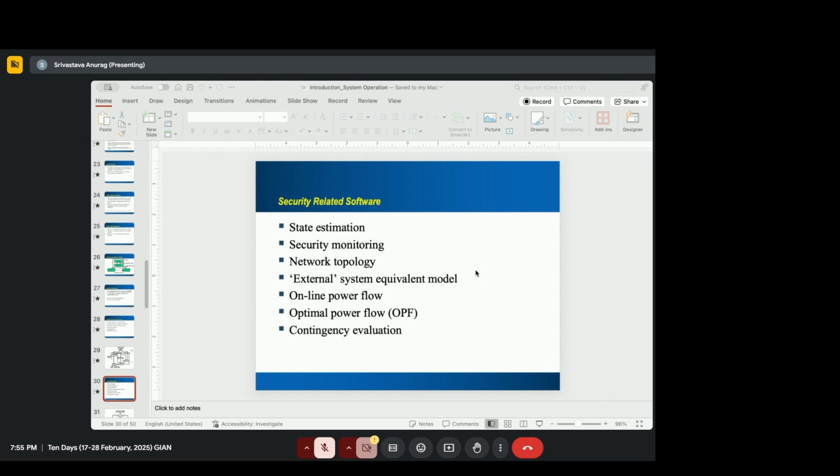Okay, going to the next question. How frequently is the load forecast updated in distributed state estimation or security analysis? So load forecast is at the same scale at which we solve power flow, right? So it's in minutes, typically 5 minutes, 10 minutes, 15 minutes, depending on different practices in the utility.